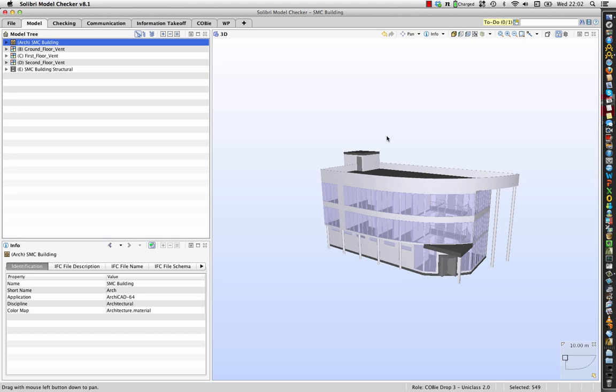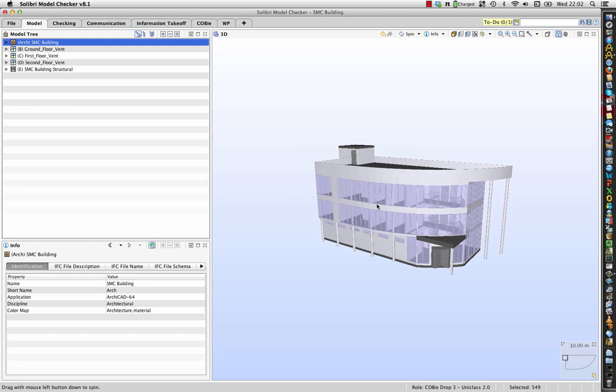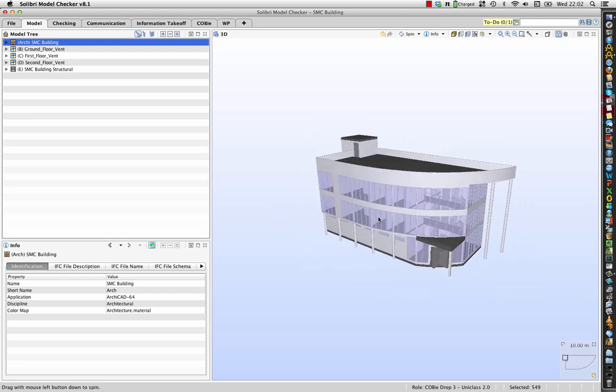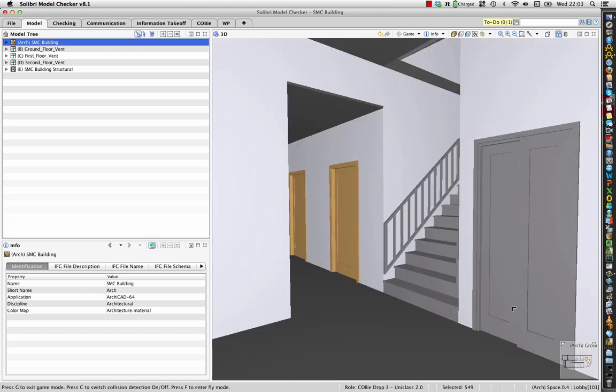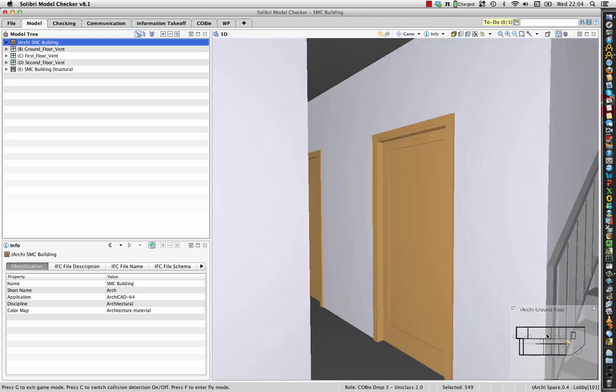Taking a closer look, navigation in the 3D environment follows the standard conventions for panning, orbiting, and zooming. The navigation map can be expanded and can be used by double-clicking on a location in the map to transport the user to that location in the building information model.